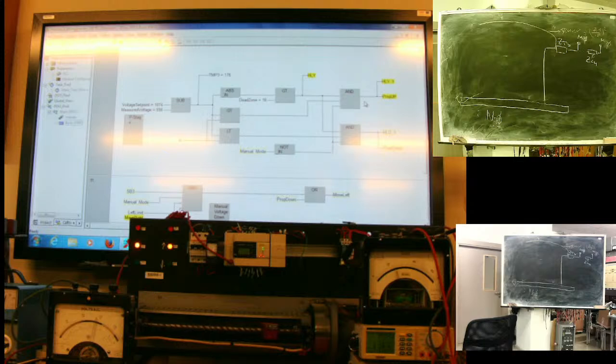For the system, change of primary voltage is the same as change of load. System tries to keep voltage stable. I increase voltage on the primary side, and control system pushes it down.